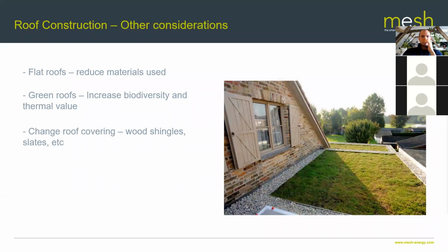The other thing to consider here as well as pitch roof alternatives are flat roof alternatives. Just from a materials usage point of view, hopefully it's obvious to you guys that whilst this may not be spatially the right thing to do in every instance, flat roofs use less material than a pitch roof does. And because you're using less material, that allows you to reduce your embodied carbon, but also it reduces the heat loss from the building because the surface area that you're losing energy from is reduced.